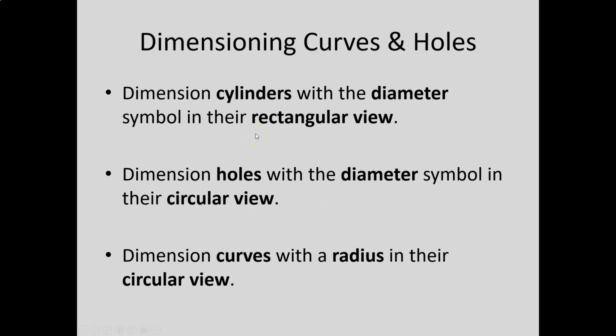This was already mentioned in the other presentation, but it bears repeating. Dimension cylinders with a diameter in their rectangular view. Dimension holes with a diameter in their circular view. Dimension curves with a radius in their circular view.